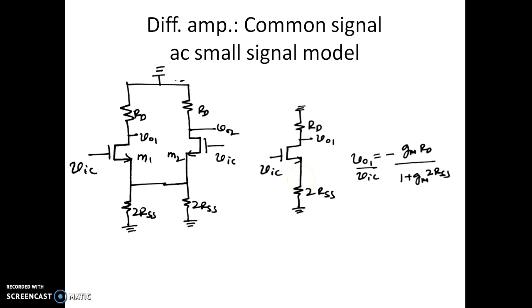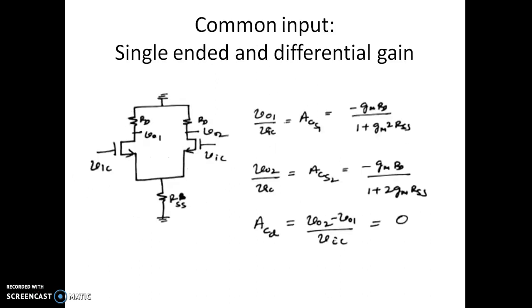For a common mode signal, the gain of the amplifier is totally different compared to the differential input voltage. If you measure the output voltages VO1 and VO2, you will be surprised. Both single-ended output voltages VO1 and VO2 have a negative sign, because both are CS amplifier solutions.